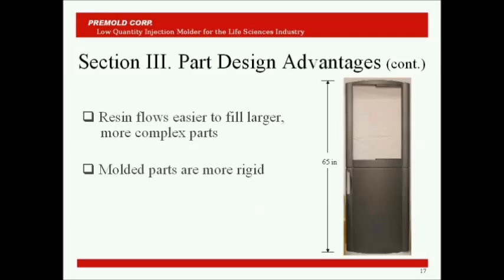You can also get foamed resins in the RIM process, and these leave you with a solid inner and outer skin on the part and a slight foaming action in between those walls, and that allows you to really keep the stiffness up while keeping the part weight and the part cost down.